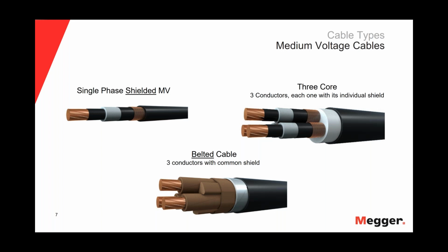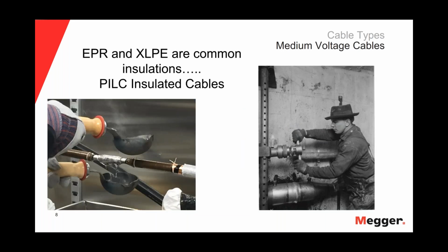And when Henning goes into his presentation, he'll probably dive into a little bit more detail on these different construction types. And as mentioned, EPR and XLPE are common installations that we see today, but there's still quite a bit of paper-lead insulated cables out there.